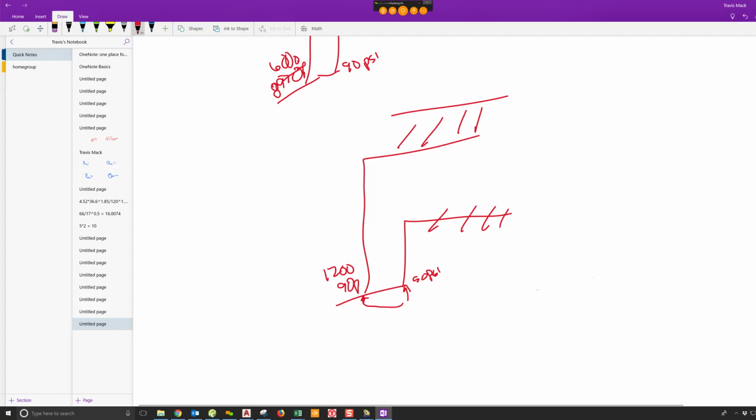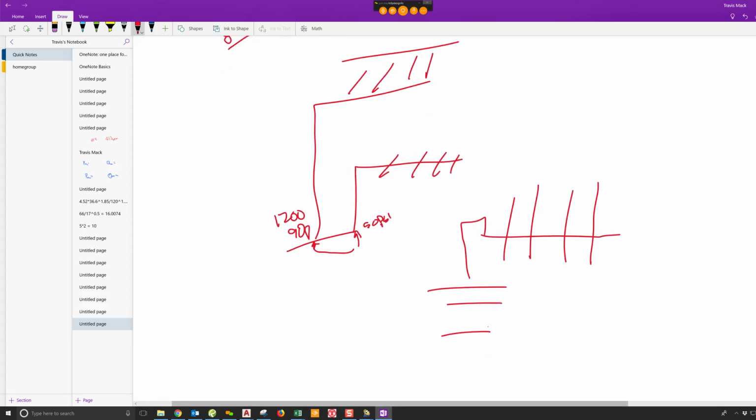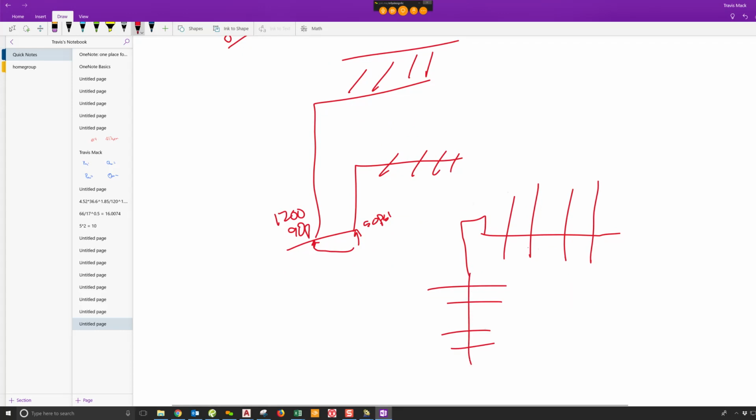I know this because I just had a job where I was helping a guy and he had some dry system. It was kind of sitting like this here. And then it did some funky loop around. And he had to basically do all this to get his 2,535 square foot. And his riser was right here. This ended up needing like 40 pounds here. And this, when it came through, was like 50 pounds. So it was over discharging everything like crazy, and he couldn't figure out how to work. He calls me up. He's like, dude, I've got 8-inch pipe in a light hazard attic, and I still can't make it work. Because he would open this up at over discharge, and things were going back and forth.